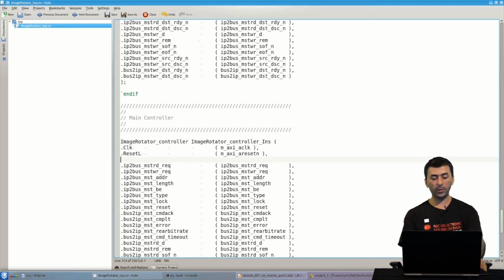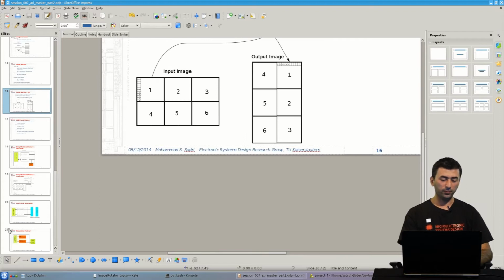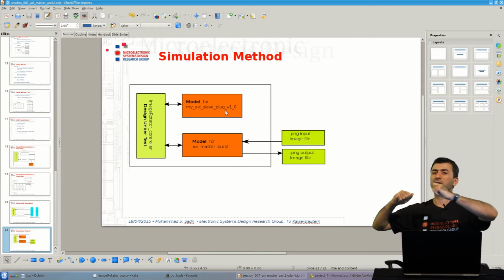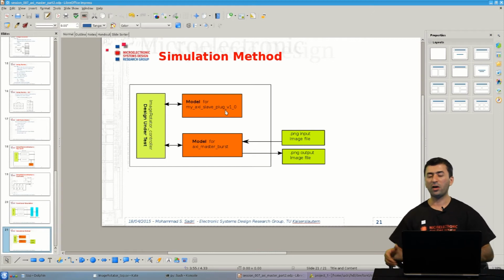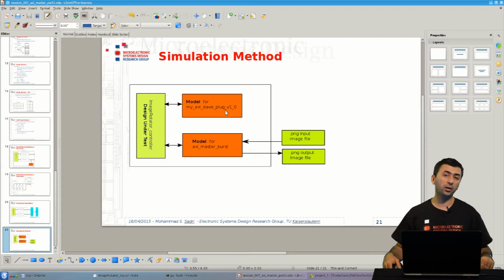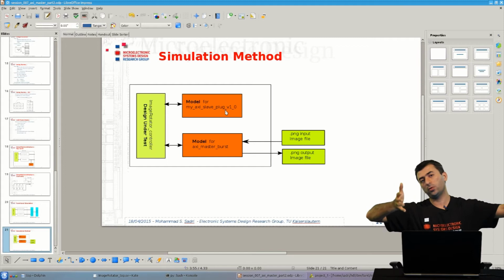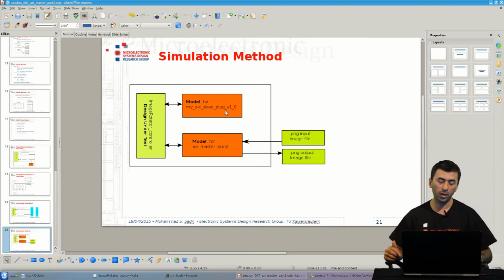If I go back to the presentation that I had in the previous session, what I told you was that if you have access to the ZYNQ virtual simulation environment of Cadence, or you have models of the PS somehow, or you have access to bus functional models of Xilinx, you have the license, you can provide them, then maybe it's a very good idea to add them to your simulation environment and then simulate your hardware accelerator along with the bus functional models that Xilinx has provided.